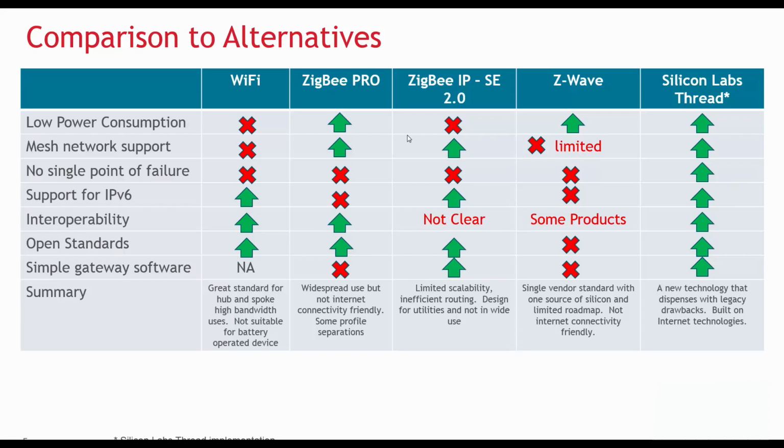That means that any communication off the local ZigBee Pro network needs a proprietary gateway to manually proxy the packets and the payload back and forth. Furthermore, the ZigBee network architecture concentrates a lot of responsibility on the network coordinator for commissioning and security, making this a potential failure point for the network.